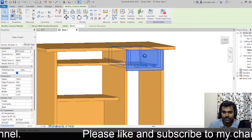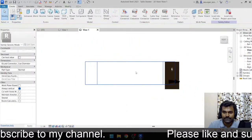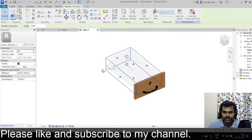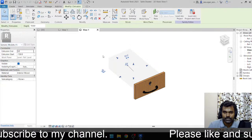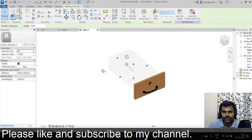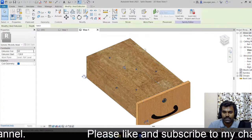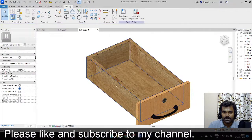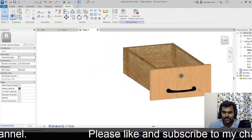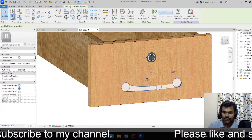Nice. If I select this drawer and go to edit family, you can see here it's a box, and finally it's an extrusion. If you select it, you can see the edit extrusion option is available. In the ribbon you can read edit extrusion, modify extrusion. It's an extrusion. I have a void family to cut this extrusion, so that's how it can look like a box. Here you can see the front piece is a separate piece, and here you see the keyhole. I have made all these families.